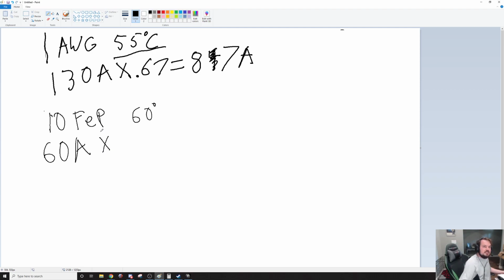You won't go back to that same table that you used, the (B)(2)(a) table. You'll go to Table 310.15(B)(2)(b), because if you look in the title of 310.15(B)(18), the one we were just directed to, you will see that it is based on an ambient temperature of 40 degrees Celsius. So you need a temperature correction factor that is based on 40 degrees Celsius.